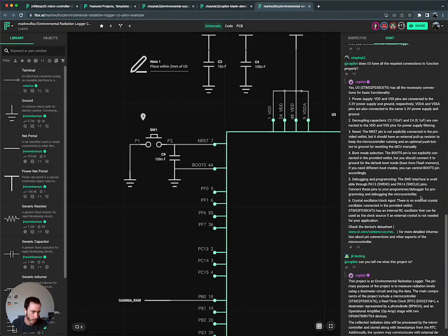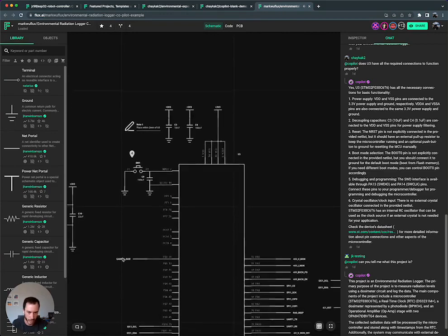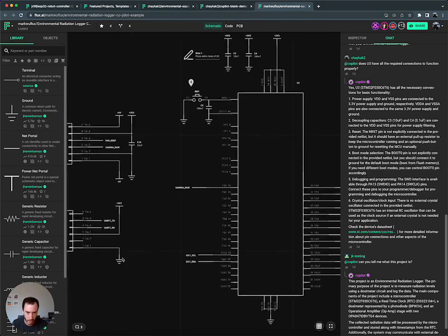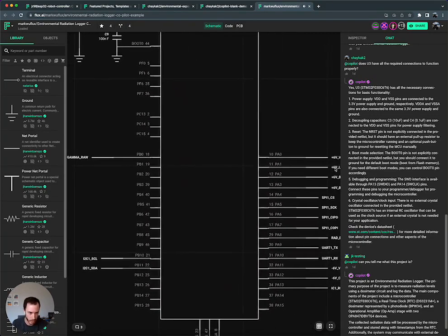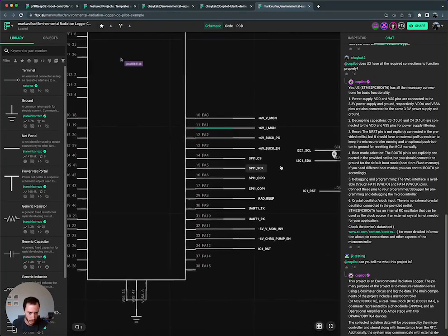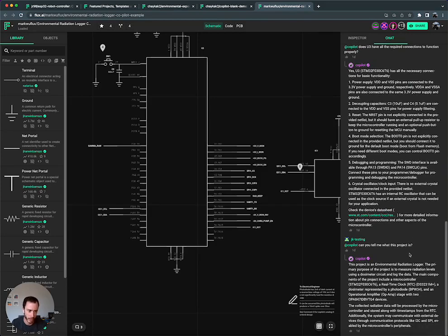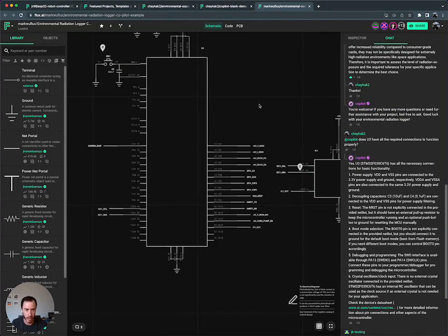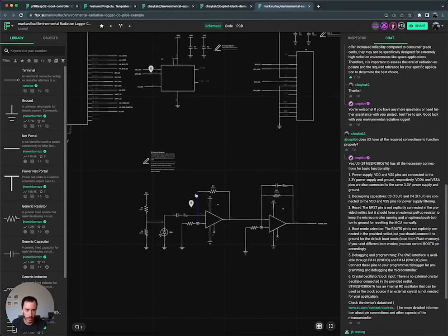Debugging and programming. Oh, looks like we don't have a programming interface defined, the SWDIO, PA13 and PA14. So let's check those out. PA13. Yeah, we're not using those as a debug interface right now, so that's actually a really good suggestion that probably we'd want to add a connector for debugging this chip as we go into it.